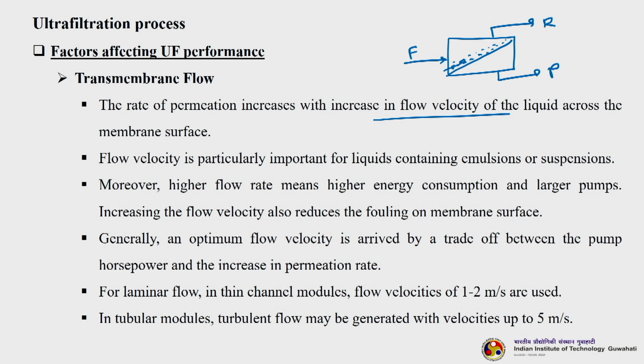Flow velocity is particularly important for liquids containing emulsions or suspensions. Moreover, higher flow rate means higher energy consumption and larger pumps. This is also not always a win-win situation: you increase the flow rate, but at the cost of what? Of course, at the cost of energy and pumping costs. Increasing the flow velocity also reduces the fouling on the membrane surface. Please understand that fouling is a consequence of the concentration polarization.